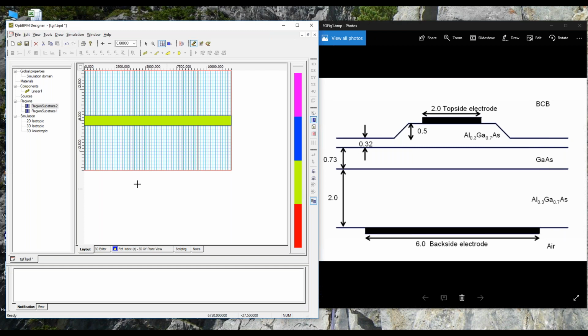And I selected, no, I don't want a second one, please. Just one will do. And I selected a propagation length of 12 millimeters because in the paper they did an experiment where they applied a voltage of 17.8 volts across the electrodes, and they observed how much propagation it would take for the optical phase to change by a factor of pi.